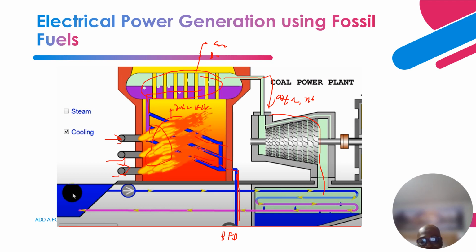Once it hits the turbine, it rotates. Then it comes down here, to the closed loop from the river. The river sends cool water that comes in touch with the steam coming back and collapses the steam into water. Then it comes back into the boiler feed pump, and the closed cycle repeats on itself.